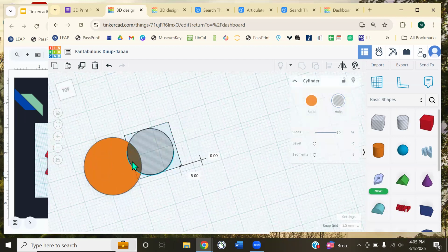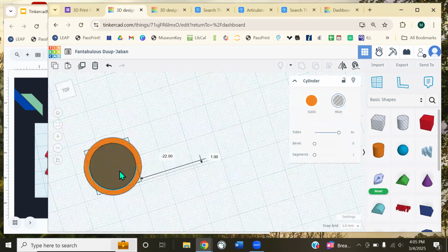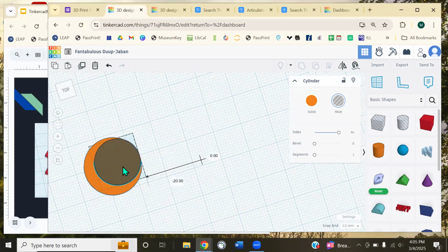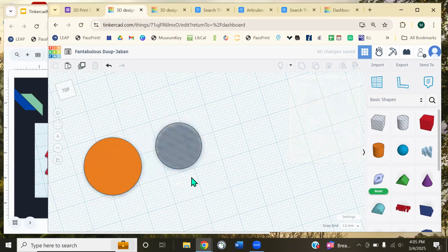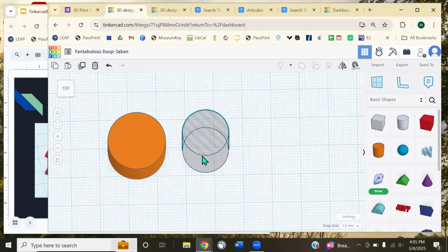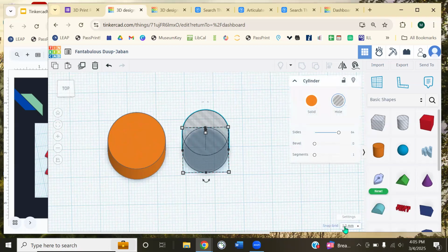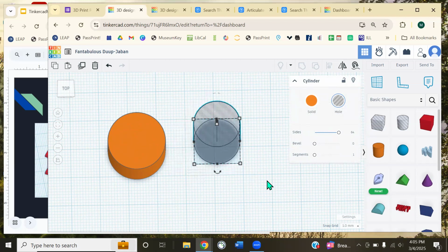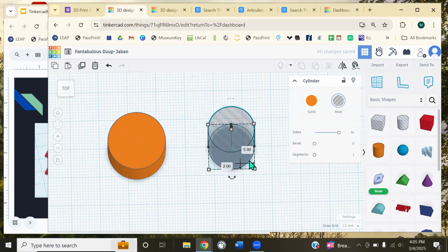And then what we can do is try to put it exactly in the middle. You can see that looks like it's exactly in the middle, but it might not be. It might be slightly off. We have a couple of tools that I'll show so we see the full tool set of the best way to do things exactly and most easily. One thing is down at the bottom, this tiny little snap grid tool, and that's affecting how many spaces up, down, left, and right an object moves when you use the arrow keys on the control pad.